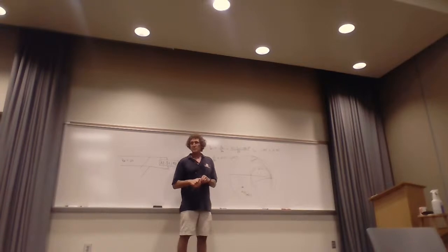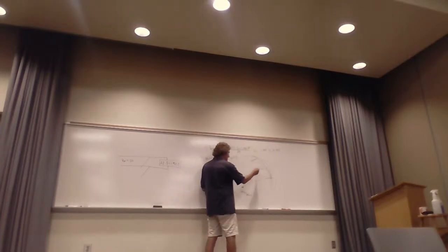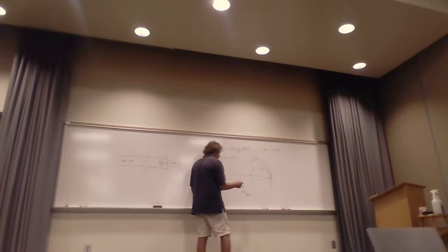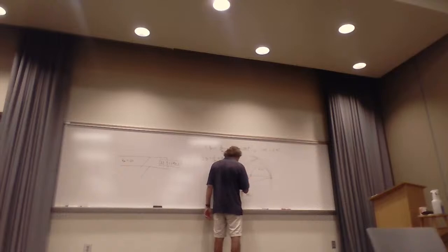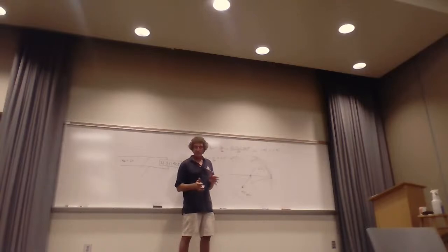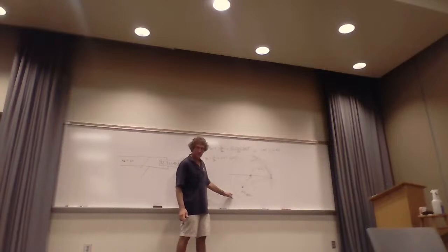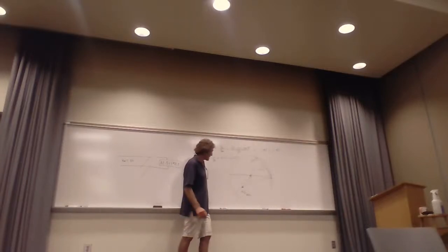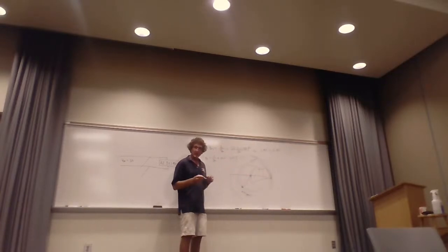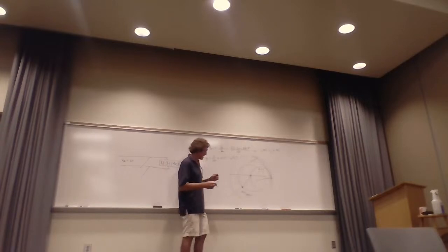I call that really the first point because you could call the conjugate point up here the first point, the Z, but you're going to go right to the opposite point. Now, this has a given radius, and the magnitude of that radius from the center is the reflection coefficient. You can read the angle down here if you want the actual angle of the reflection coefficient. Do y'all remember this stuff? All right, now you need to take a compass and make a circle of that radius. Now here's your first point.